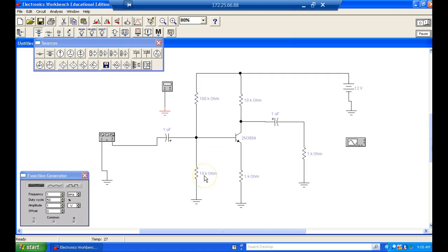What we want to do is make this one right here bigger. And that's a win-win because we increase the input impedance, so my function generator over here won't have to provide as much current. And we're not changing the gain of the amplifier. The gain of the amplifier is still going to be 10.